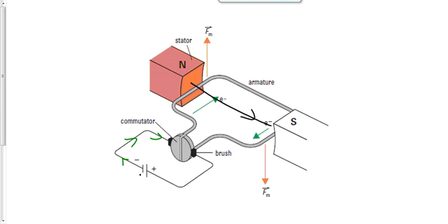So these electrons end up flowing clockwise around into this little black thing that we call a brush. That brush is touching but is not connected to this thing that we call a commutator. So in other words, the commutator is free to move, but it still all the time touches this brush. So when the commutator and the brush are oriented like they are right now in the diagram, you get an electric current going through the conducting brush, through the commutator, and it goes around here through this thing that we call an armature going clockwise. Back to the commutator on the other side, back to the brush on the other side, and then back to the battery like this. Make sense?